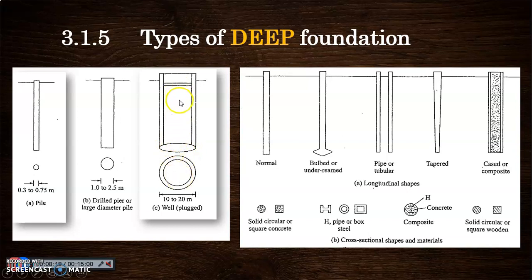When you imagine pushing these big pipes down, eventually you could have soil coming in, a plugging effect here. Moving on to the right, you have some tapered piles. These are more like the timber piles, which are not very common these days anymore because of sustainability issues. And again, we could have a pile that is composite. You push in the pipe, then you put in the concrete if you want it to be super strong. Alright?